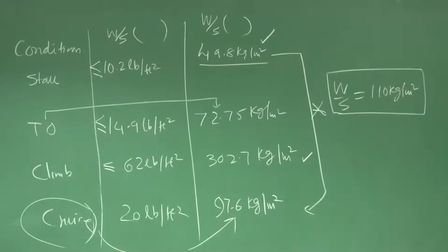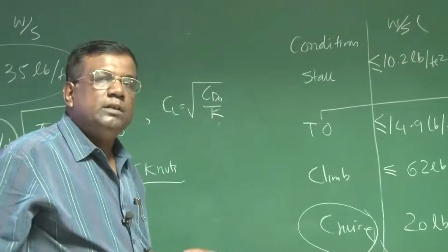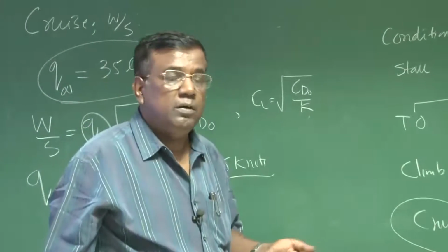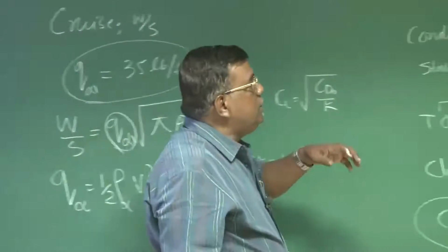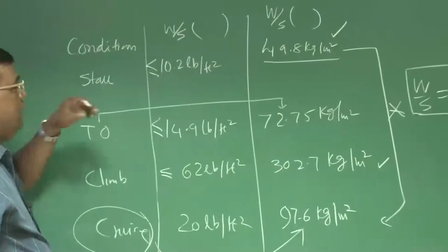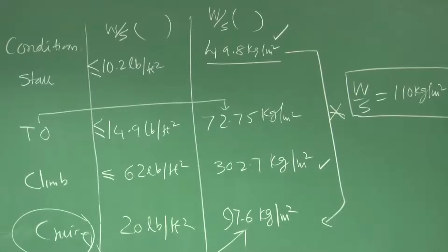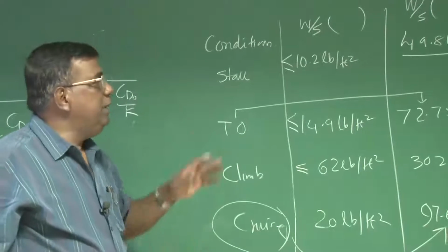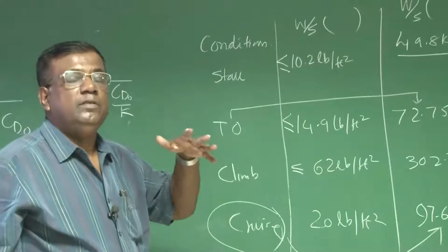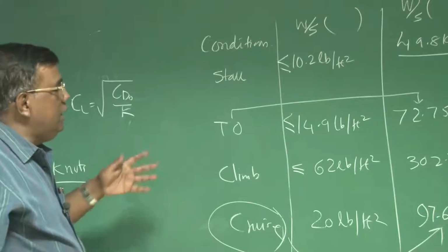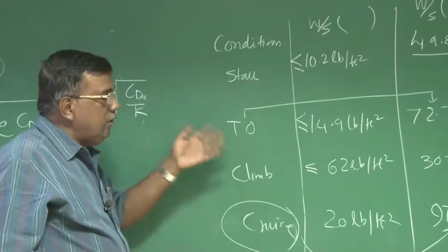Why is the lowest wing loading recommended? It means larger wing area, right? But you understand larger wing area means larger span, because you need to have a larger aspect ratio. Larger wing area means larger drag. So all those complications come, and then the question is, if I select the lowest wing loading criterion, I'll cross-check what mission performance it is satisfying. It is stall. If the requirement is very stringent on takeoff condition, then I may give wing loading primary importance, as long as I have exhausted all the CLmax or high lift device options, right? If it is a plane for maximum range, then why should I give so much weightage to this? So that sort of a debate will go on.